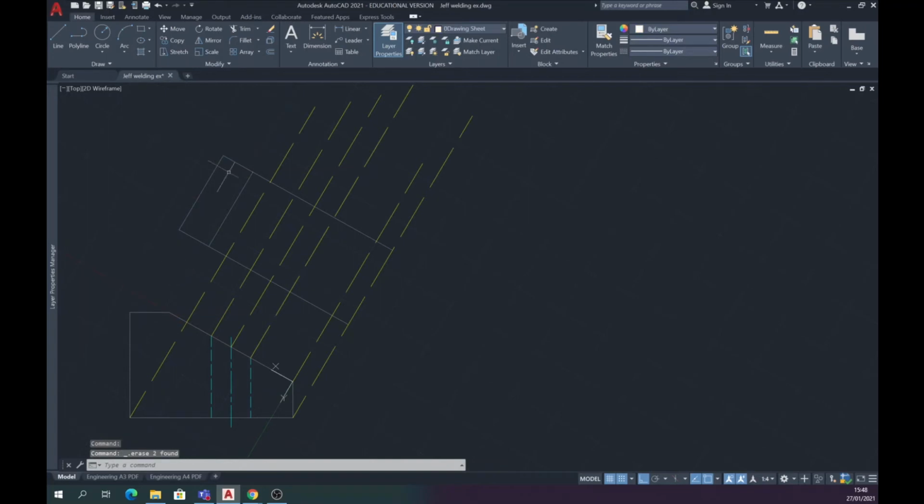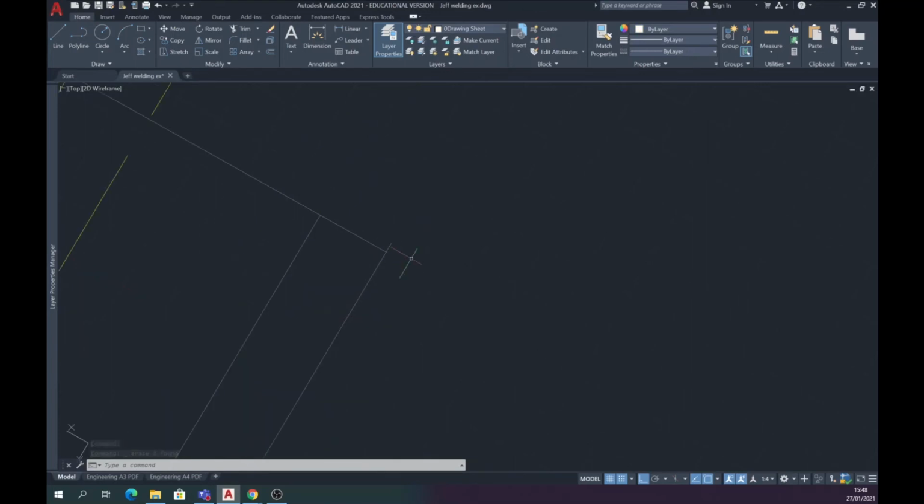So what you can see now is I have that face which represents this top edge. So I'll continue to add these in. We'll do the extremities of this. I can now remove these two projection lines, and you see I have that detail there. I must have overshot the line here somewhat, so I'll take care of that just now, simply by using the grip and dragging it back to the extent.